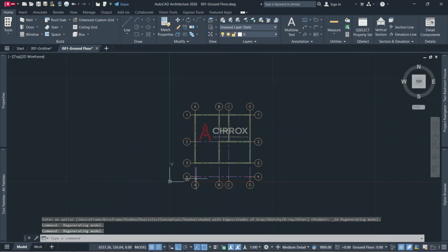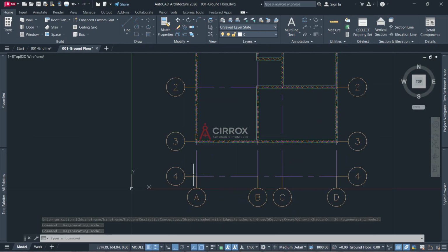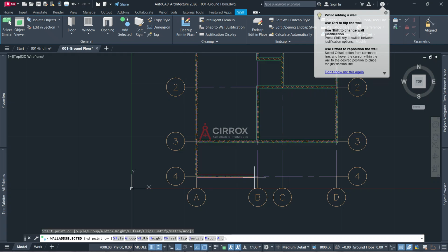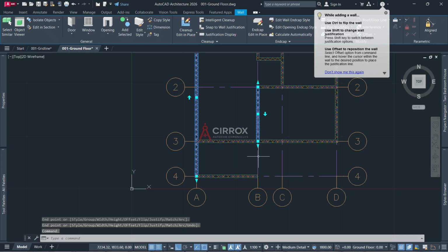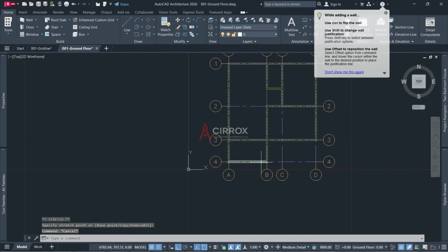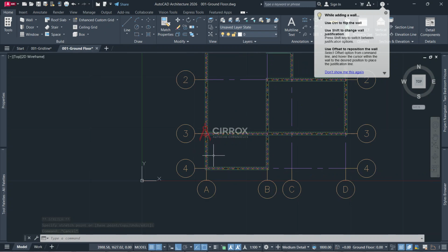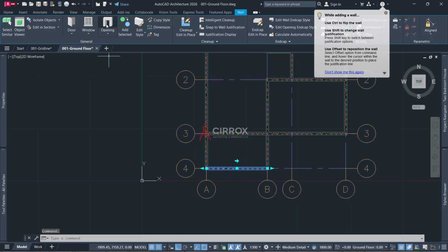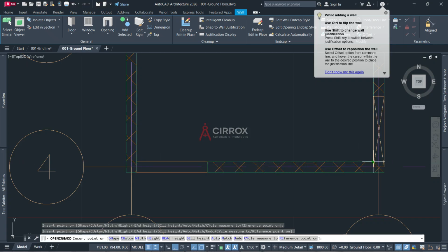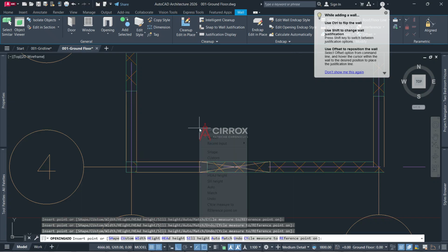So I have a porch over here. To create a porch, I'm going to extend this wall to this place. I selected to this place, and I'm going to extend this wall again to that place. Alright. So now I have extended my walls, and I now need to create an opening in here. So I'll select the wall, then I click on openings in here. Then now you can see I'm having an opening here, and opening here too, and opening here.